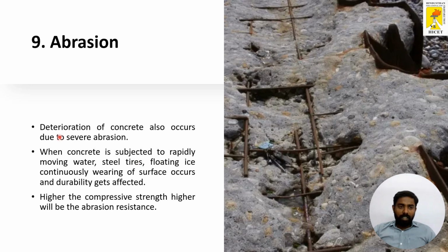Next one, abrasion. Deterioration of the concrete also occurs due to severe abrasion. When the concrete is subjected to rapidly moving water, steel tires, floating ice, continuous wearing of the surface occurs and durability gets affected. The higher the compressive strength, the higher the abrasion resistance.